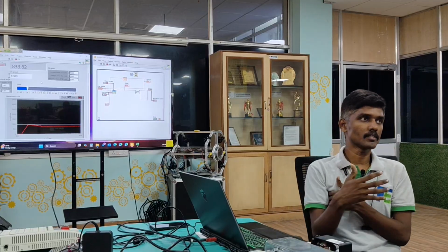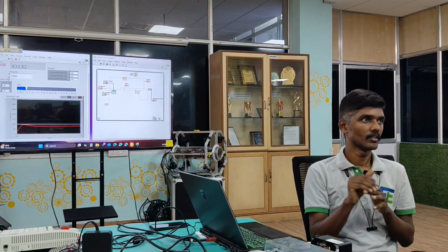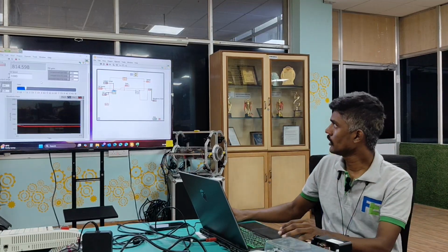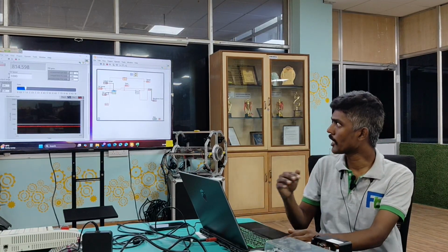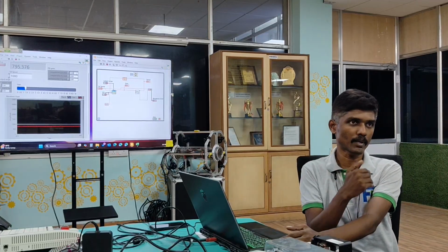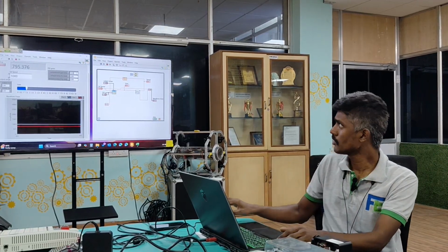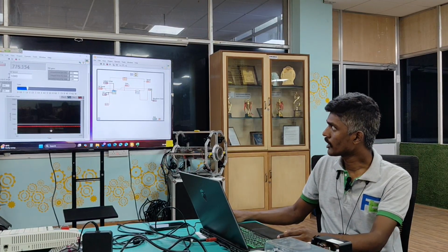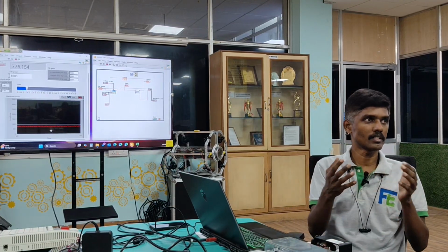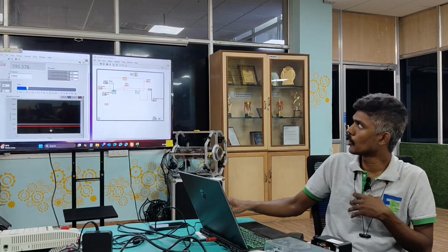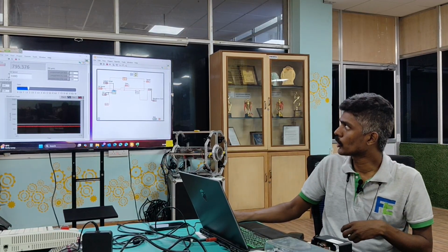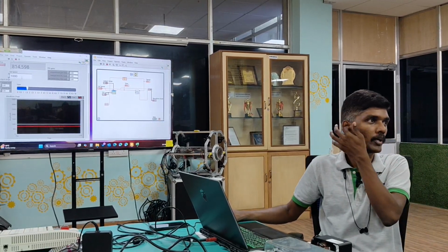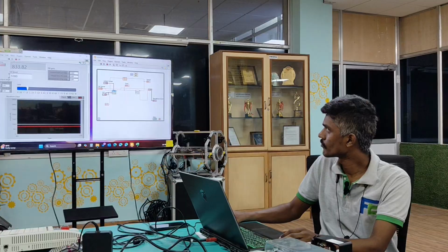Initially I am keeping this proportional gain value as 0, and the remaining Ki and Kd values I will keep as 0. So initially I am slowly increasing my gain value from 0.001 to 0.002, 0.003. I kept it at 0.8. Whenever I set 0.008, I am trying to get the constant error. Constant error in the sense your variable in the output is something like 790 to 820 and 1000. Nearly 180 to 200 RPM a constant error.